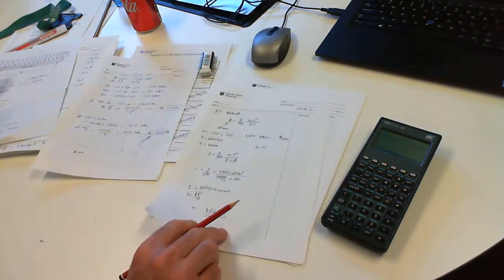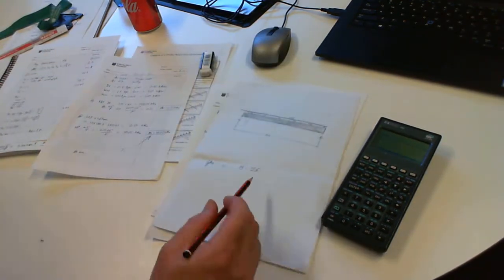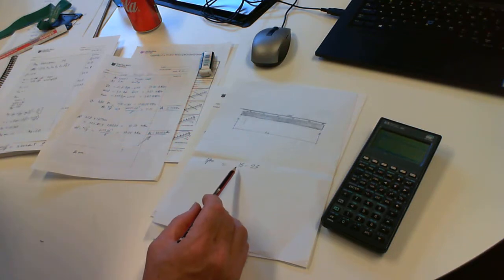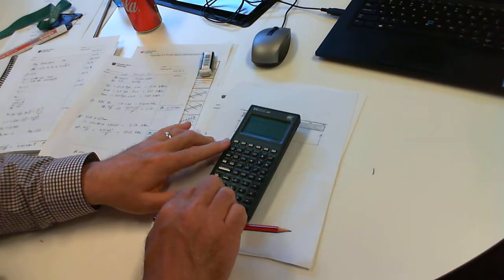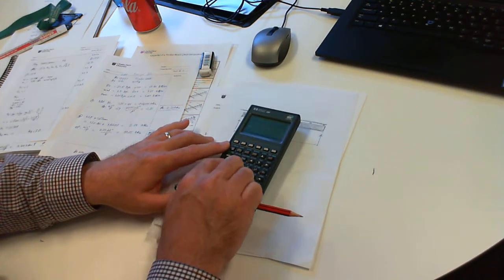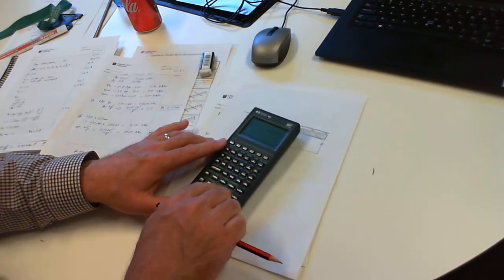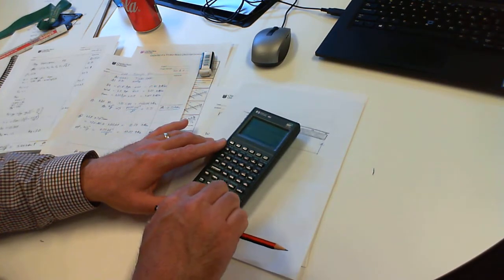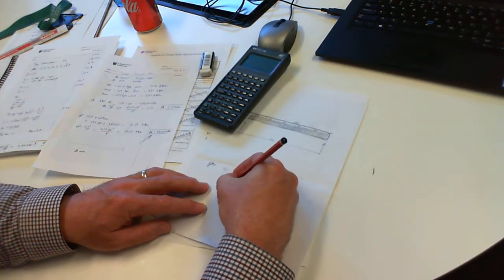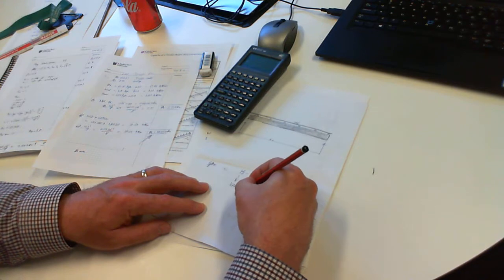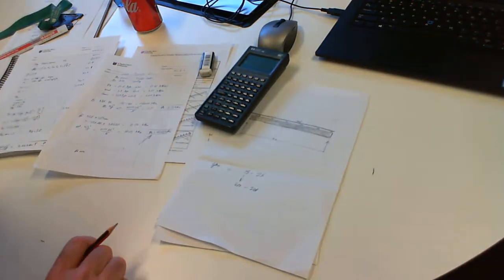Now, it's also worth mentioning that you should check this against ratios. For a regular timber beam, you should be looking at a span to depth ratio of 15 to 25. So if I got 6,000 millimeter span, if I divide that by 15, that's 400. If I divide that by 25, that's about 240. So I should be looking at a beam somewhere between 240 millimeters deep and 400 millimeters deep.